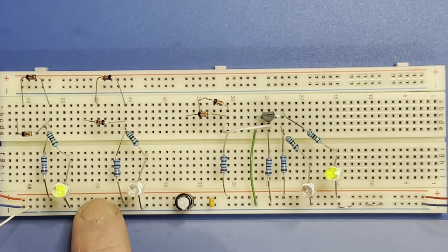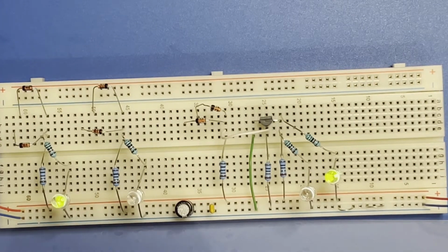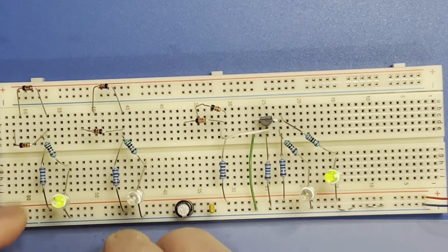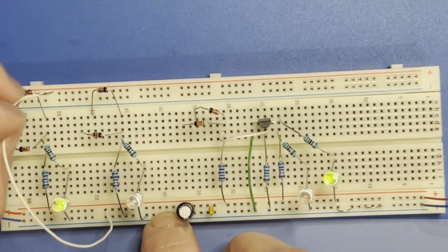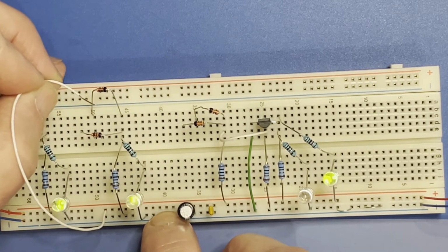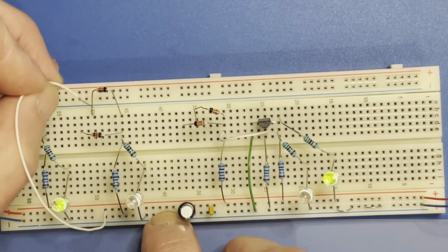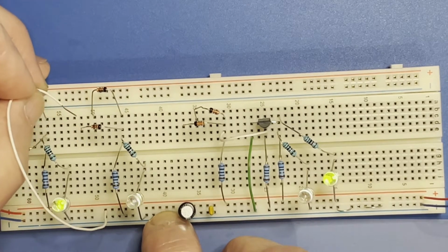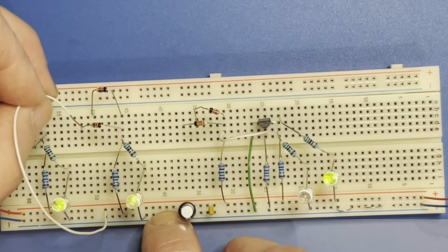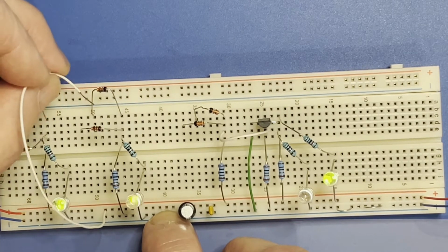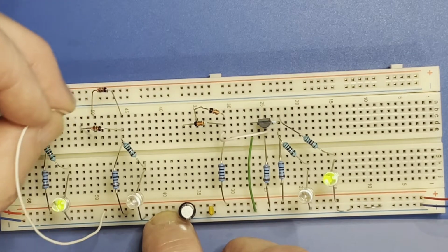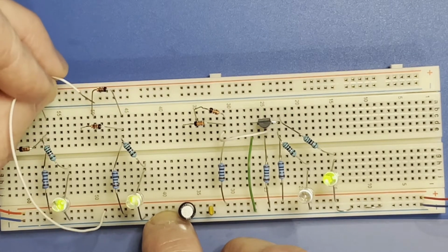So that will function in itself as an OR gate. If I connect power to either input, the output goes high, the LED switches on. You see again the inputs are 2 separate tracks, and you can have any number of diodes you like, all connected to that common point as the output, and it will work.